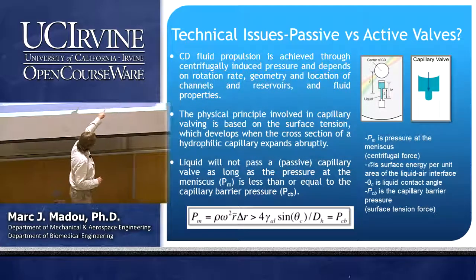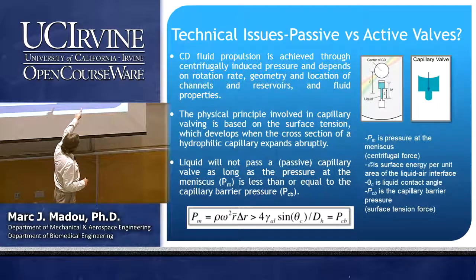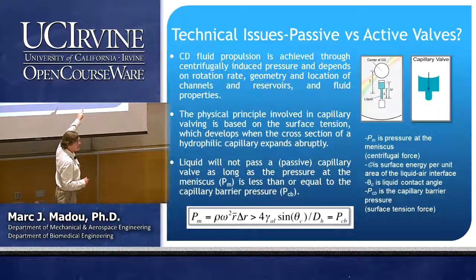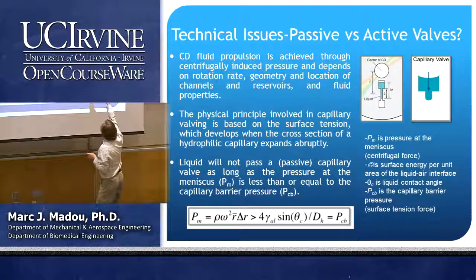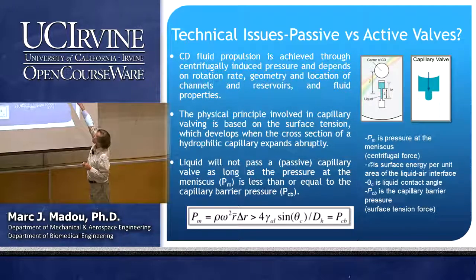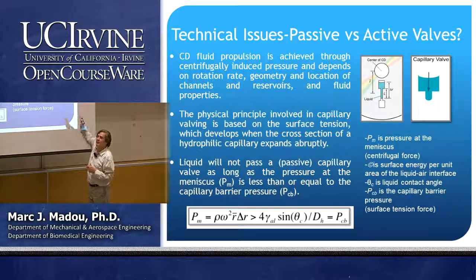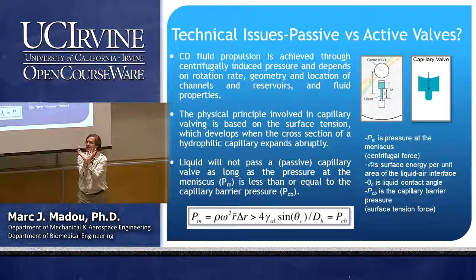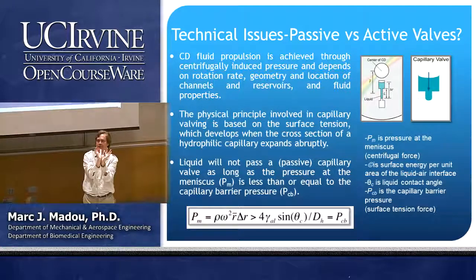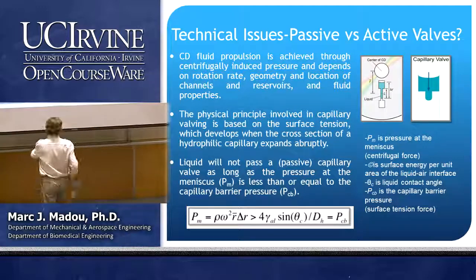Now, the picture on the right describes how a liquid will get pinned and cannot escape till you go fast enough so that that bubble bursts. We call that the burst frequency. So I want to calculate how fast I need to spin this CD for the centripetal force to overcome the liquid tension, the energy keeping that bubble together. And that expression is given here.